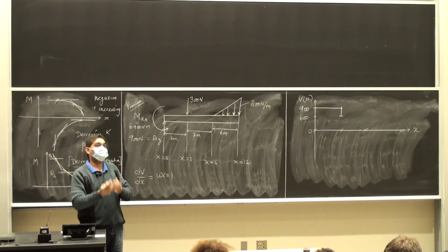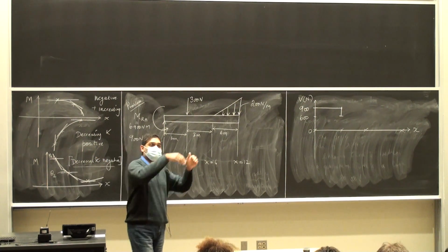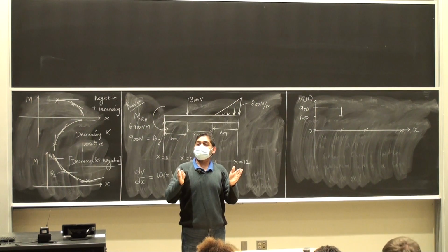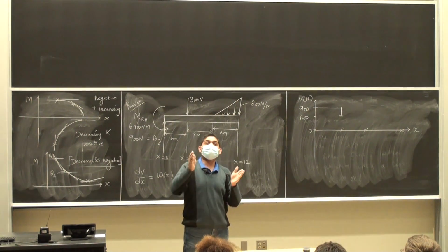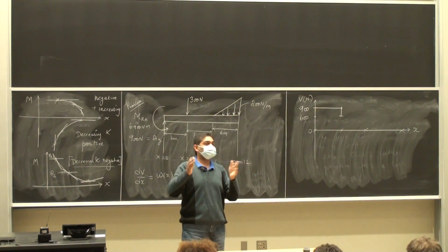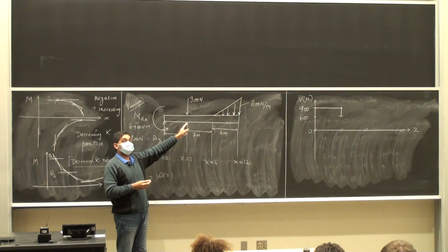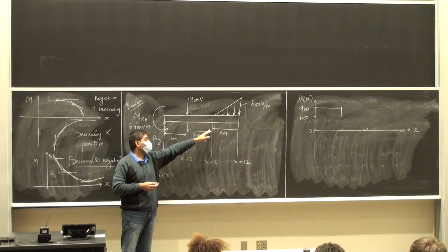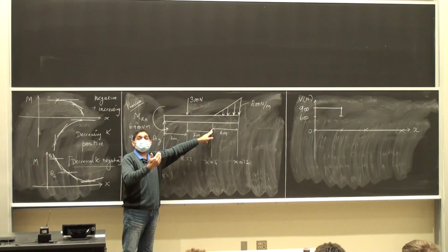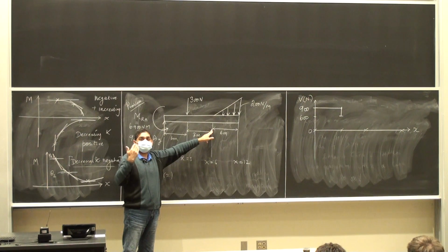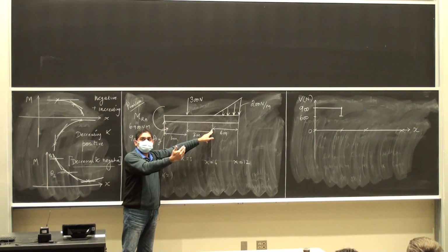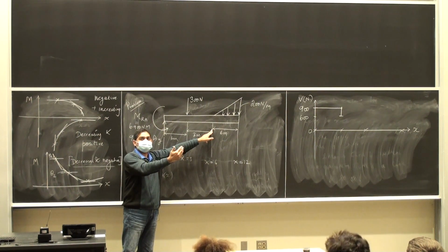If I see a force pointing up, pushing me up. If I see a force pointing down, pushing me down. If I see a distributed loading, it will align me in some direction. Okay? Then easy journey ahead, 3 meters, all the way to 6 meters before the start of the distributed load. What do I do? Constant 0. Straight line. 0 slope, straight line.